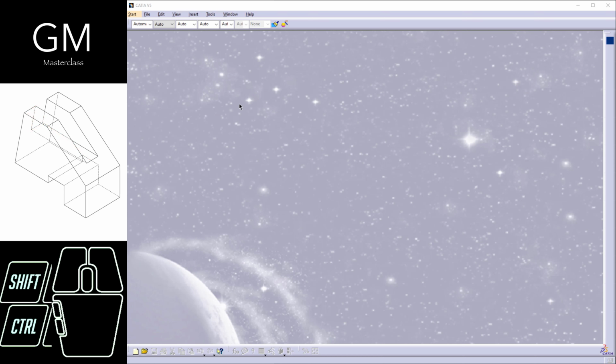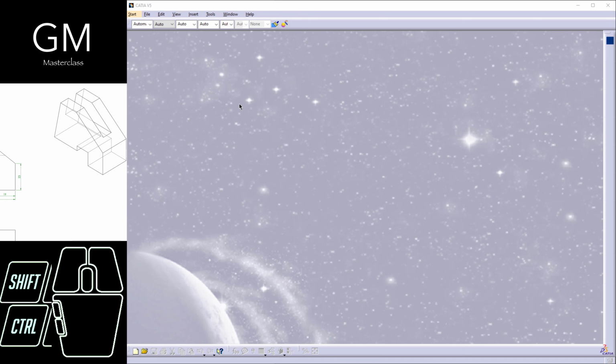Okay, the first thing that we have to take into account here is the engineering draw, and within it the views. In this case, I can see a mistake right here, and it's this view. Why is that? Because this view does not contain information about the 3D model. So if it's not necessary, then I don't have to put it, and if I put it, it's a mistake.